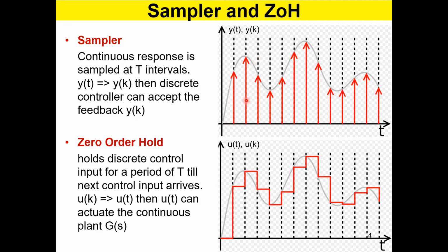That is the sampling interval. So once you specify, okay, my sampling interval is 1 second, then you can talk about the samples y0, y1, y2, y3, y4, right? In the discrete version, this capital T sampling interval does not appear all the time. Only briefly, where you talk about sampling interval, it comes there and it goes to the equations, different places. After that, you don't see it.